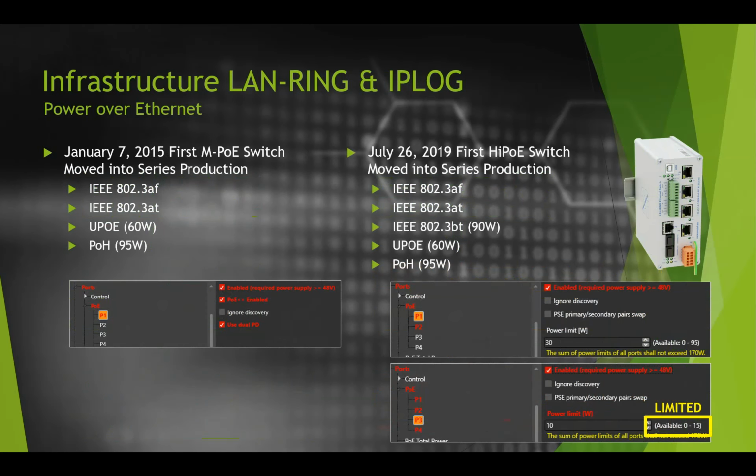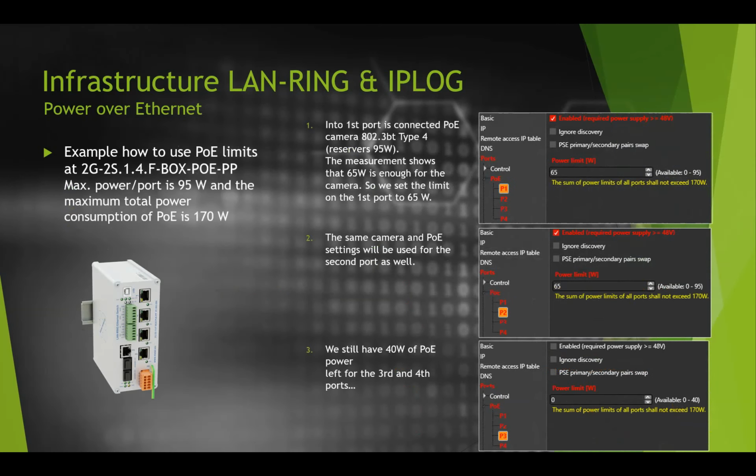We present two values for PoE switches: maximum delivered power from one port, and maximum delivered power through all ports. The maximum delivered PoE power per port can be further limited by setting in the configuration software. In practice, this can help, for example, to protect the system from overloading the power supply in the event of a PoE camera failure. The status of the PoE power supply can also be monitored using the SNMP protocol.